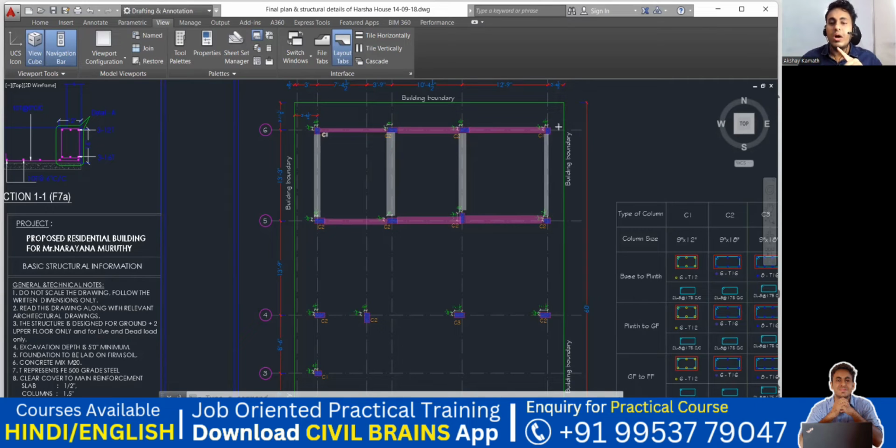Okay. Got it. Now, is it necessary for you to connect this column in this direction? Plinth beam, not at all required. Why? Because you don't have anything here. Just in case if there was one more column, then you could have connected that.